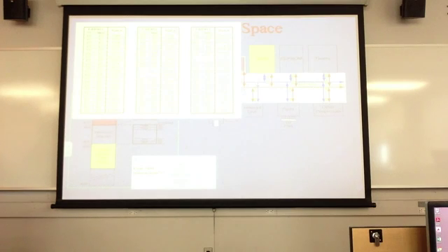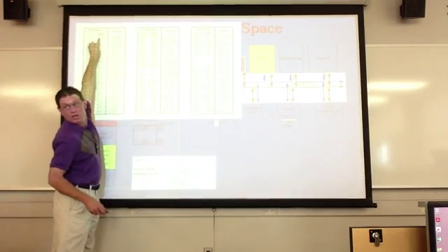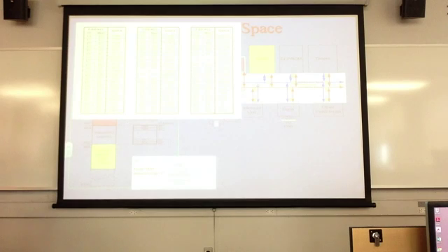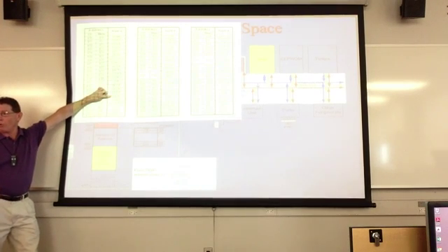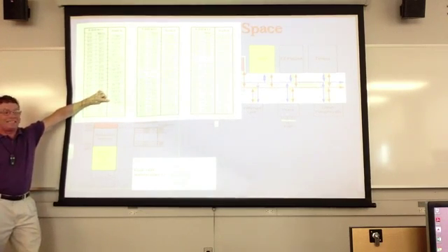Now again, for the 169P, this is all of the registers. You have two types of addresses going on here. The IO address starts at 00, but the physical memory address starts at 020, which is denoted right here. That number is the physical memory location, okay? And you'll see all these names in here: TWBR, ADCL, ADCH, and PIND, which is used to control port D as an input. The data direction register for port D is here. This is how you select port D.